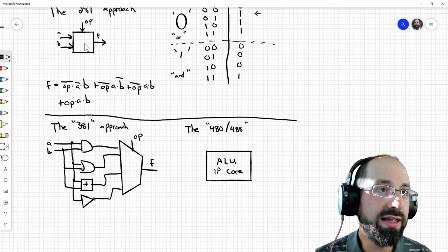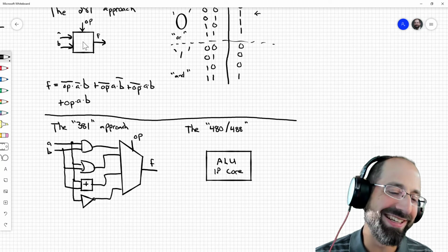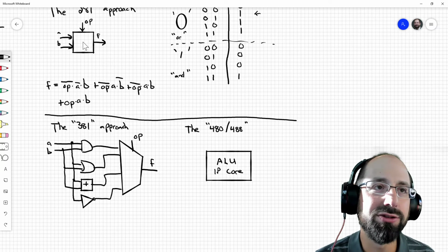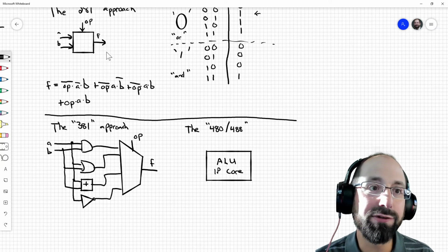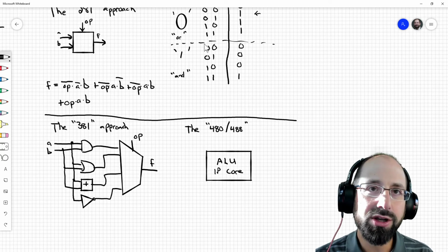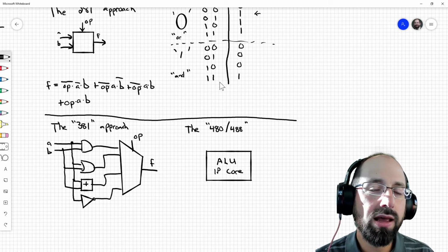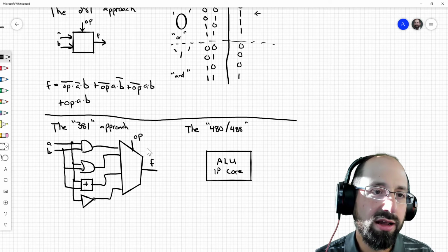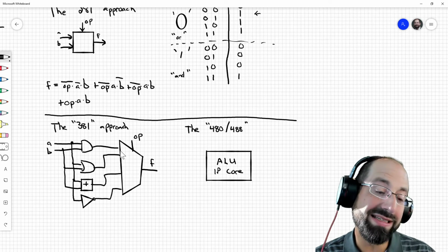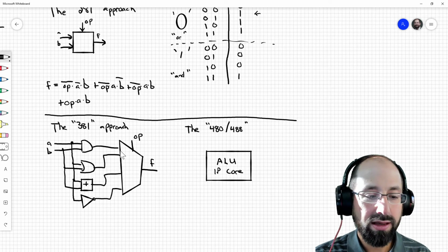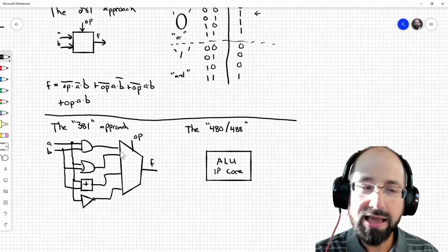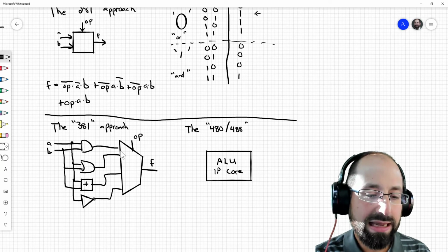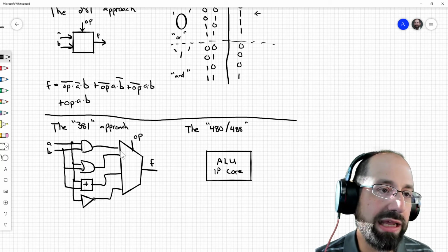But when you're dealing with this, there's only so many gates you can generate in a day, right? I mean, the more you try to do, the more likely you'll introduce a bug along the way. And even if the circuit is resulting the same, you're operating at a pretty low level, and you're caring a lot about should there be a gate here or a gate there. The 381 approach is essentially what data has to route through my circuit, what size mux do I need, how do I control the inputs to that mux, and you're more productive than in the 281 approach.